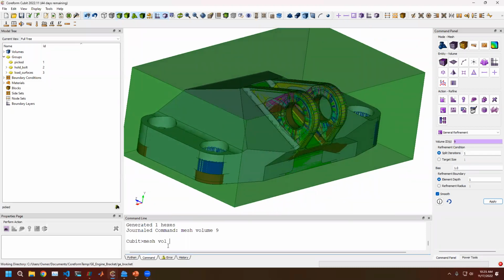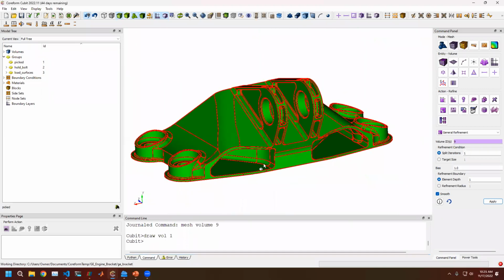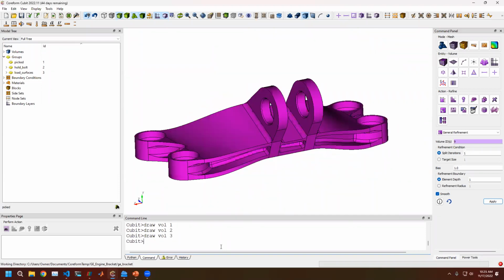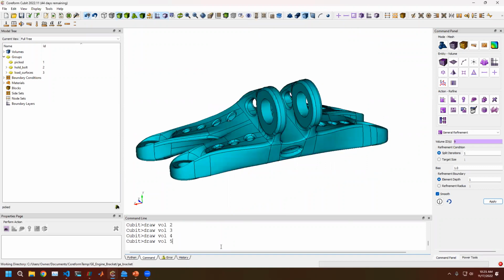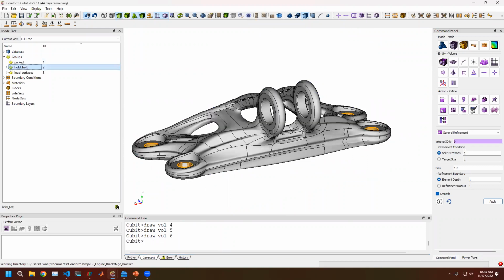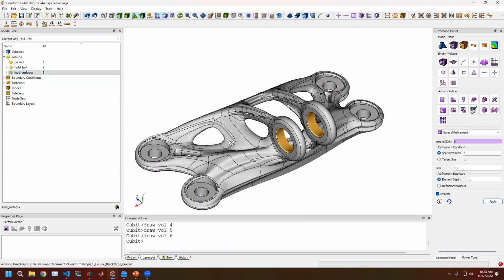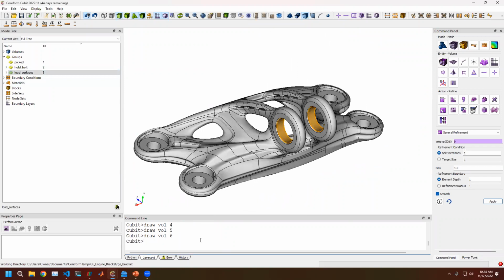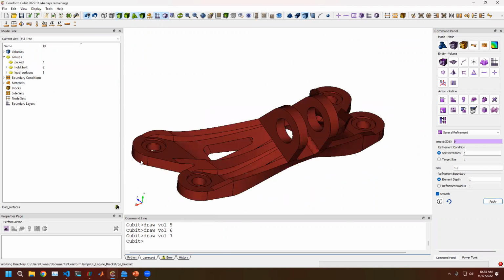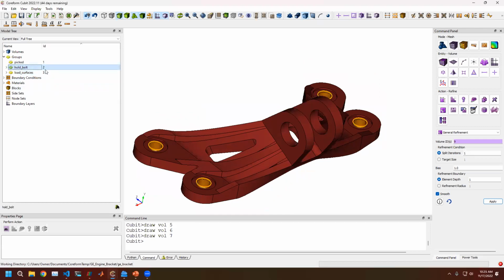In this case, this is the winning entry, and these are actually the top, I think, 7 results. Because they all fit that same space, that workflow is the exact same for all of them. I've got those bolt surfaces and the load surfaces all selected if I want. So it becomes trivial to do that setup.